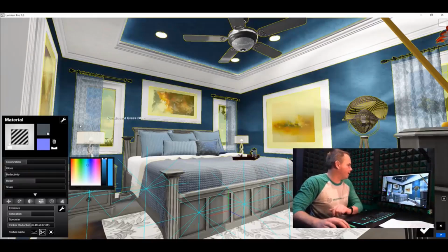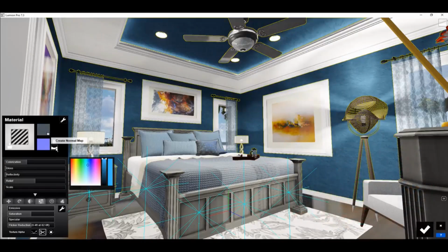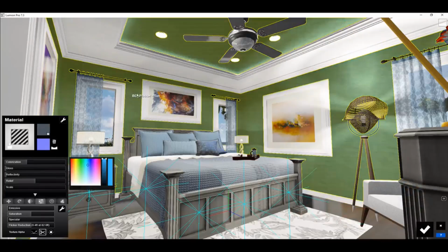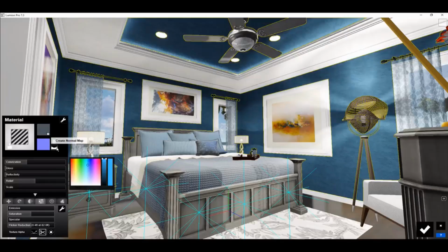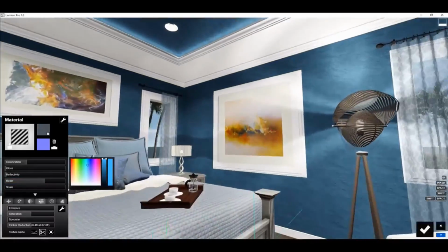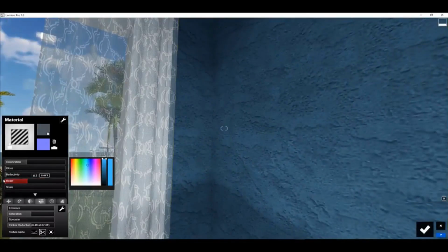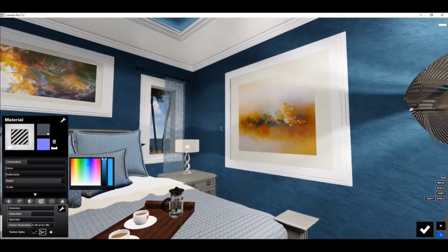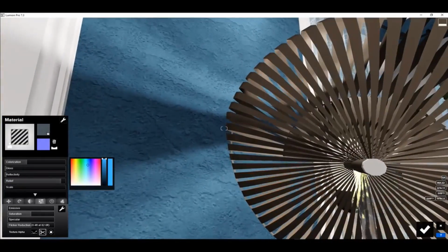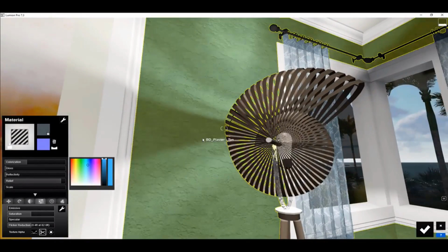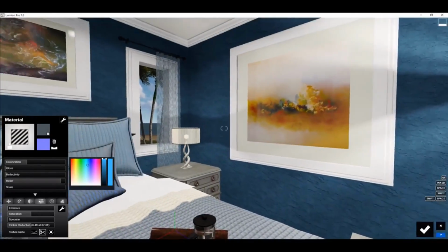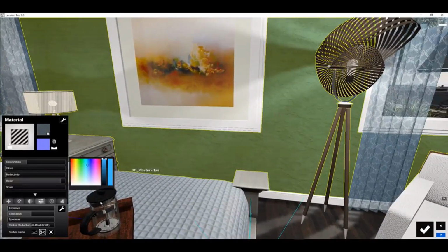So definitely one way to do that is just click this Create Normal Map. That is a button in Lumion. Like this is a SketchUp texture. I can click on Create Normal Map, and then the way to control that is with relief. Sometimes it's kind of hard to see the relief actually happening unless you have some sunlight on it, or maybe a good preview, but I think I can see that happening. I'm going to flip the direction. So anyway, that's one way to do it. All right, then we should see some nicer effects happening, with the normal map being applied there. Actually, I think I am seeing it pretty heavy down there.